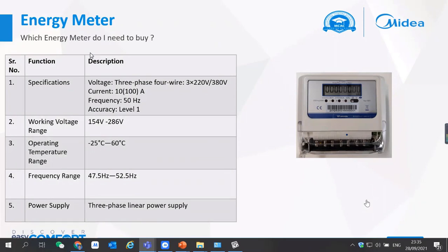The new diagnosis software works on the new protocol XYE that has the outdoor and indoor information together. So if you want to connect the old protocol that has XYE and K1 K2 separate, then you need to connect a converter board that joins XYE and K1 K2 into a single XYE, and then use it on the new generation software.